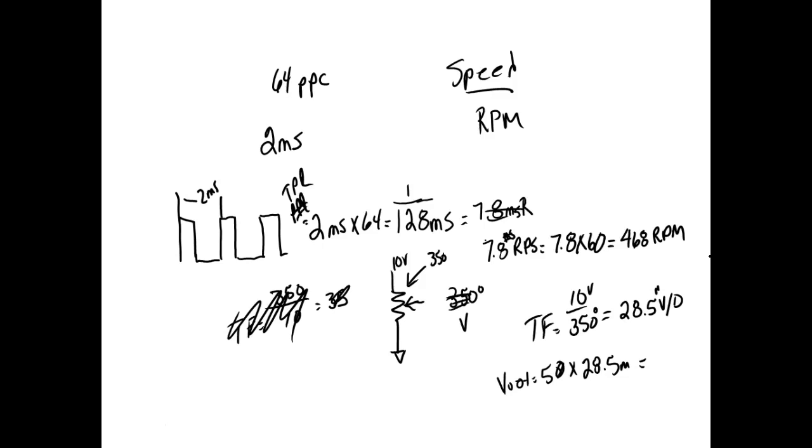If I don't know the transfer function and I measure the output of a sensor and I get 6 volts, what does that mean to you? It's a temperature sensor. What does that mean to you? It means absolutely nothing, right? Unless I knew 6 volts equals 130 degrees, that's where it comes into play. You understand that? So that's what it means.